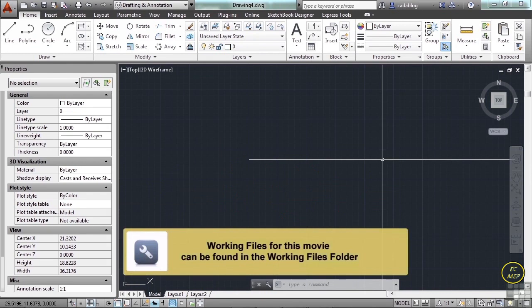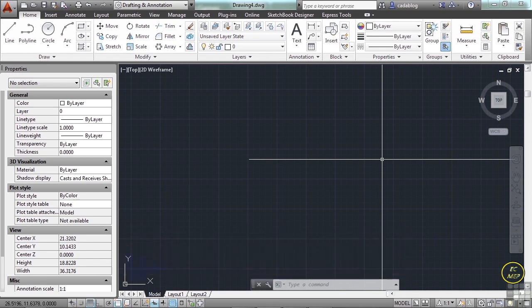As we have discussed in several sections and chapters, model information goes into model space and annotations go in paper space. In order to annotate anything, we need to have the model visible in paper space. That's done through viewports. Think of a viewport as a window to model space or a photograph of that model that you can label. Since each viewport is its own photo, we can do anything we want to them, and they won't affect anything else, not the model nor the other viewports.